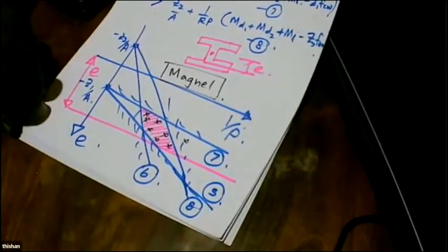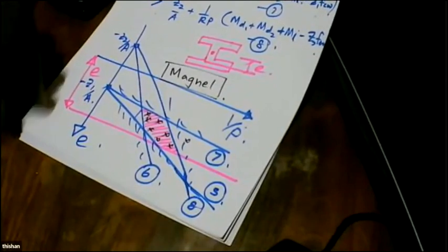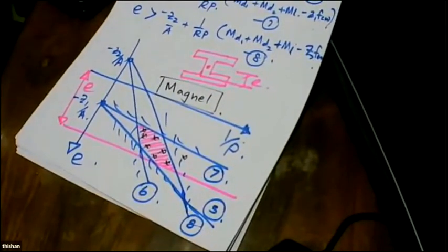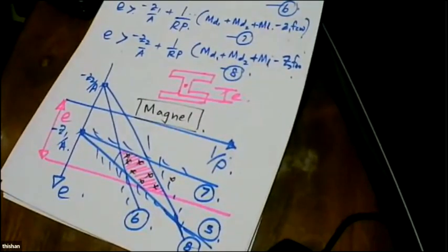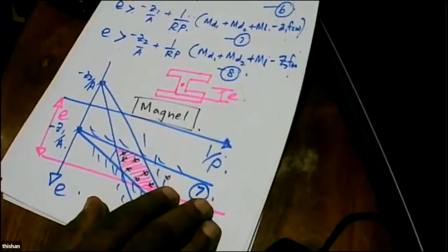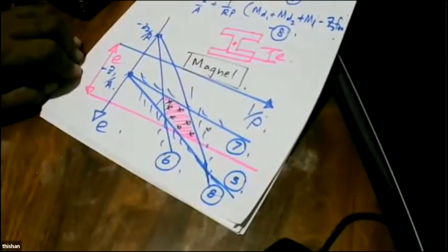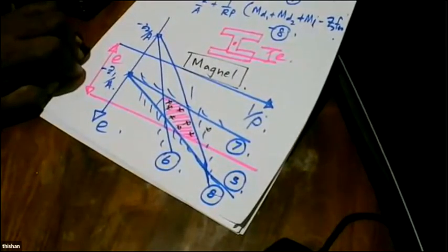So this is the theory of pre-stress concrete, and you can see, this is the basis that we use when we are designing pre-stress concrete beams. Because we don't worry too much about the equations, we simply draw the equations as a diagram, a graphical representation, and then we select a point inside.